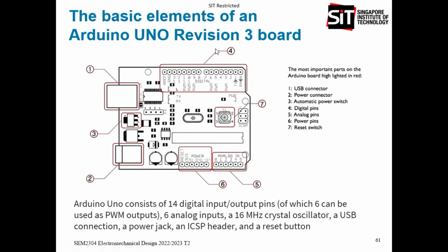Can you program the Arduino analog pin to do a digital function? Yeah. Same, can you program a digital pin to do analog? Cannot. But an analog pin, you can use it to program for digital. Why is it that you cannot? The digital pin doesn't have ADCs and DACs. So that's why you cannot program digital pins to do an analog function. But for analog pins, we can program them to give voltage high, voltage low, and that will be the same as your digital pin.